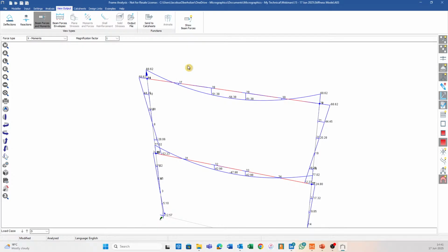There are cases where a connection will be seen as infinitely stiff, to which I go, yeah, cool, that is fixed. It is infinitely stiff in a specific direction, though. But then we go, okay, cool, that connection is fixed. But I hope that what you've seen through here is that it's not as simple necessarily as saying a connection is pinned or fixed, because it's not really either. It's somewhere in the middle, and it tends more towards pinned, or it tends more towards fixed. But it's not perfectly either of them. It will never be.